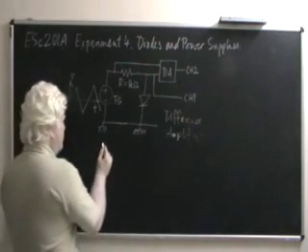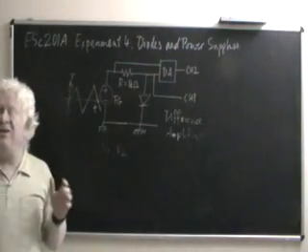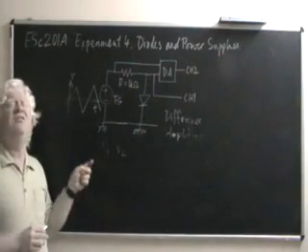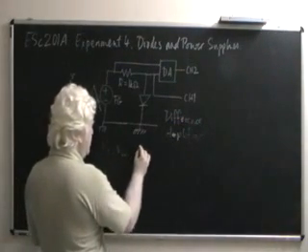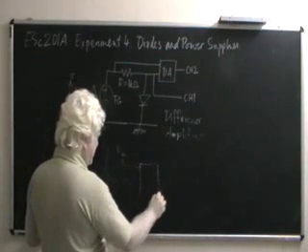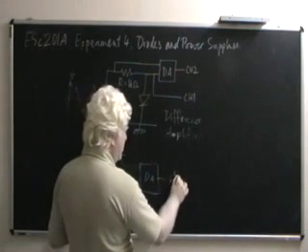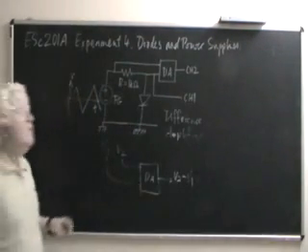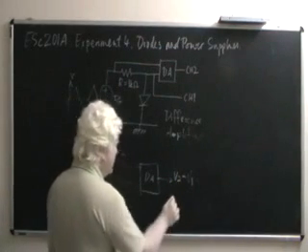let's say V1 and V2. V1, V2 are two voltages in a circuit. Neither of them is a ground voltage. Both these values are with respect to the ground, and on accepting these two inputs, V1 and let's say V2, the difference amplifier produces V2 minus V1 with respect to ground. It produces a single voltage which is measured with respect to ground.